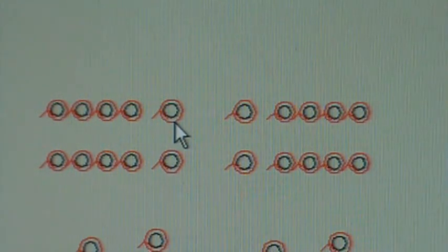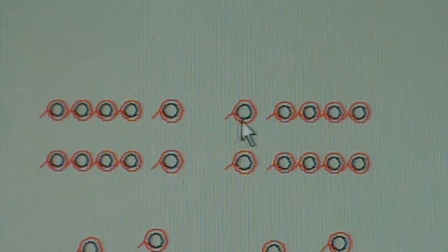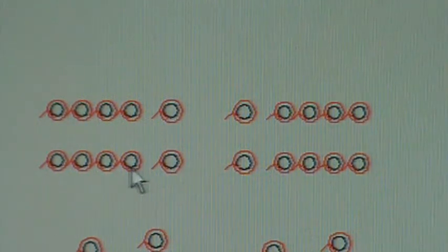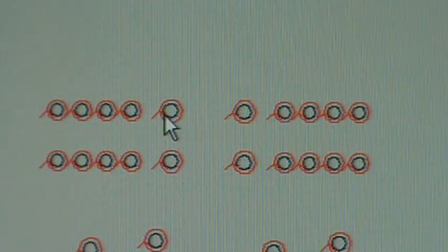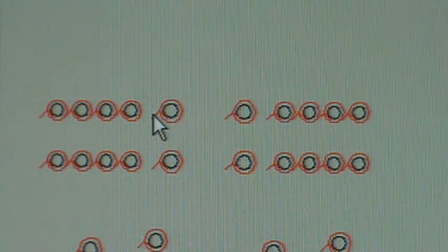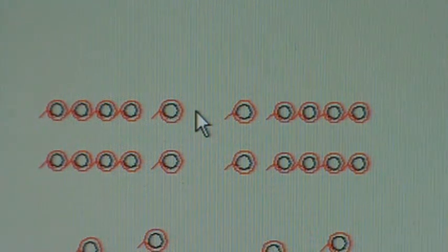So when you have all your arrows pointing one direction, it puts all of the red cutter center lines on the outside of it. But if you do that, your hole is going to be bigger. It's going to be bigger by 1/16 of an inch because you've got a 32nd on this side and a 32nd on this side that's cutting out. So if you want an 1/8 inch hole, it's actually going to end up 1/4 inch because now you're adding 1/8 of an inch of cutting width on either side.